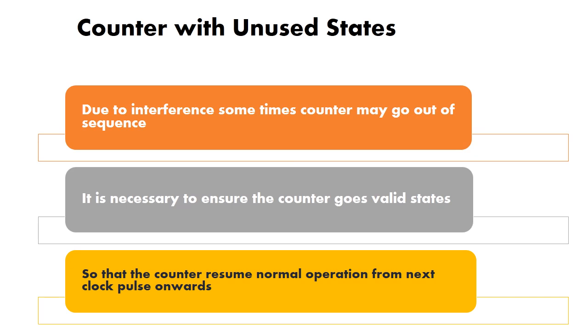However, once a circuit is designed, outside noise may cause the circuit to enter into an unused state. In that case, it is necessary to bring the circuit back into the original sequence of states during the next clock pulse. Otherwise, that circuit becomes useless.